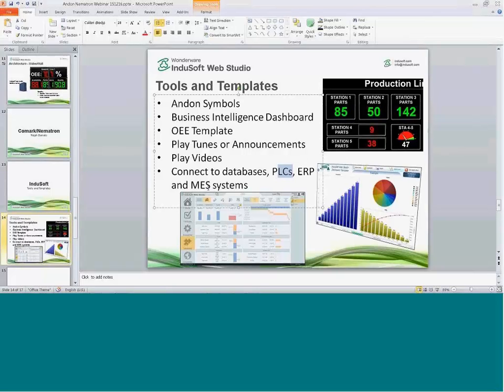Earlier this year, I did a project where we were grabbing information from a Siemens PLC, Schneider PLC, simultaneously putting that on the screen, and then their production data system, so a SQL database, and then being able to show that spread across 19 different monitors hanging from the rafters. Was kind of a really neat application to be able to grab all of that information from all of those different sources and be able to display that.